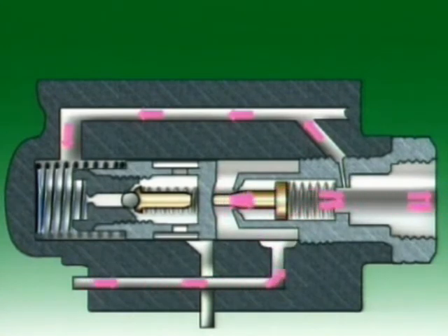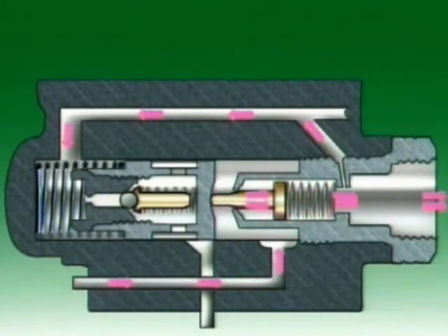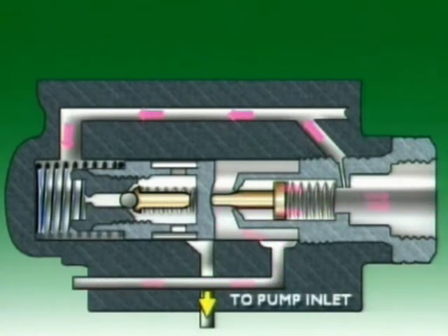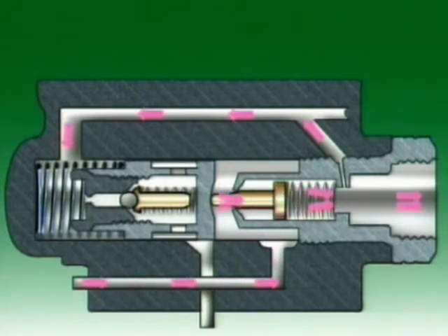The pressure difference on the valve causes it to move away from the outlet fitting, but the force of the spring prevents it moving far enough to uncover a return port back to the pump inlet. Movement of the control valve controls the position of the needle valve in the outlet fitting, and this controls the fluid flow to the steering gear.